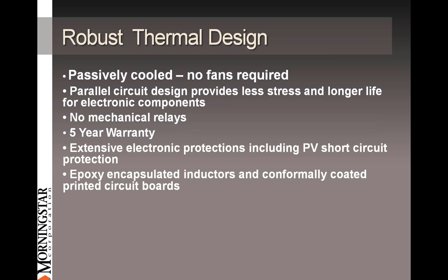We also don't use any mechanical relays. Most controllers use a mechanical relay on the PV input. We have an all solid state connection, meaning we're using power MOSFETs there. The advantage there, of course, is mechanical relays fail. MOSFETs last quite long. And also, because of that, we don't have that extra power draw that a coil requires. Most importantly, as you see in the next feature, we have very extensive electronic protections, including the ability to provide PV short circuit protection. Because we don't use a relay, you can't really short circuit protect a relay. They're too slow.